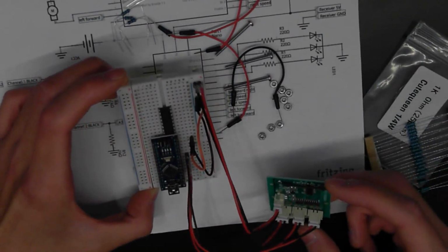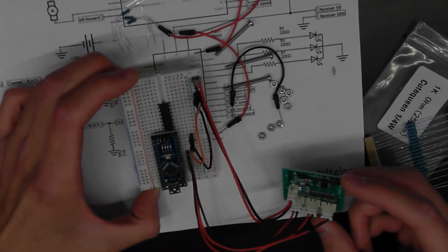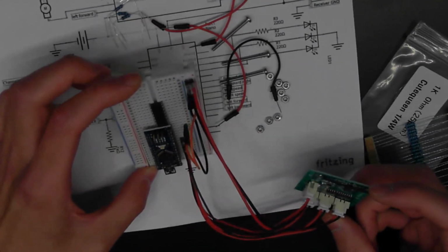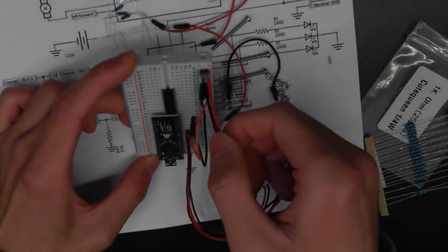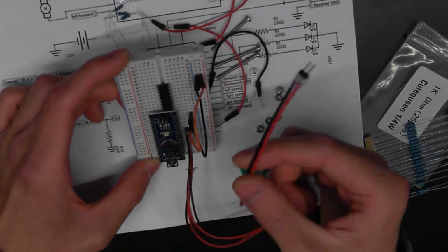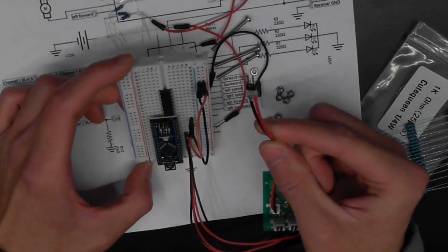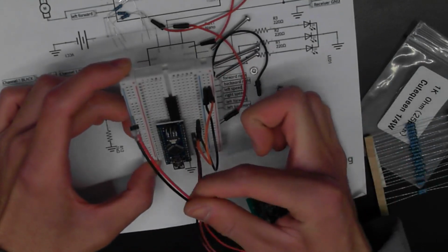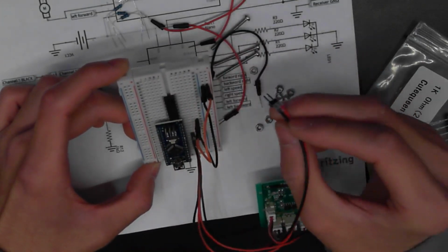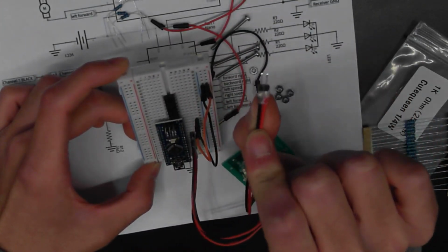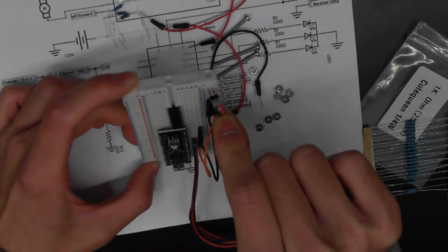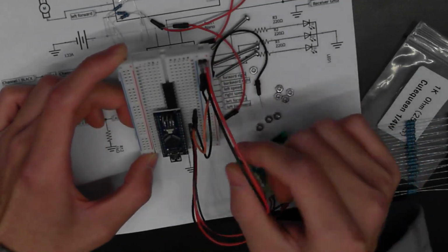And I think your receivers should be disconnected. So let's connect them up now. So remember from last workshop, the right side of this breadboard is our 5-volt line. This receiver can only take up to 6 volts, so make sure to not connect it to the left side, as that is our 12-volt rail. We want to connect it to our 5-volt rail. So to do that, look at the black and red colors, and connect it to the header or the bus, like so.